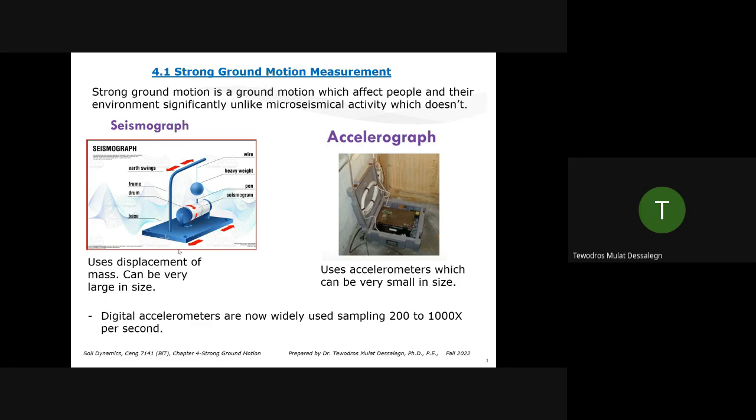And when the seismic wave comes, let's say in this direction, in the red arrow direction, it shakes the whole instrument. It has a frame with a suspended mass. This heavy mass is designed not to move. Whatever you see here, the wire, we specifically design it not to move. It has damping and stiffness properties within this wire. We specifically design it so that whatever seismic motion comes, this mass doesn't move. But the other things are rigidly mounted to the bedrock, so they move.